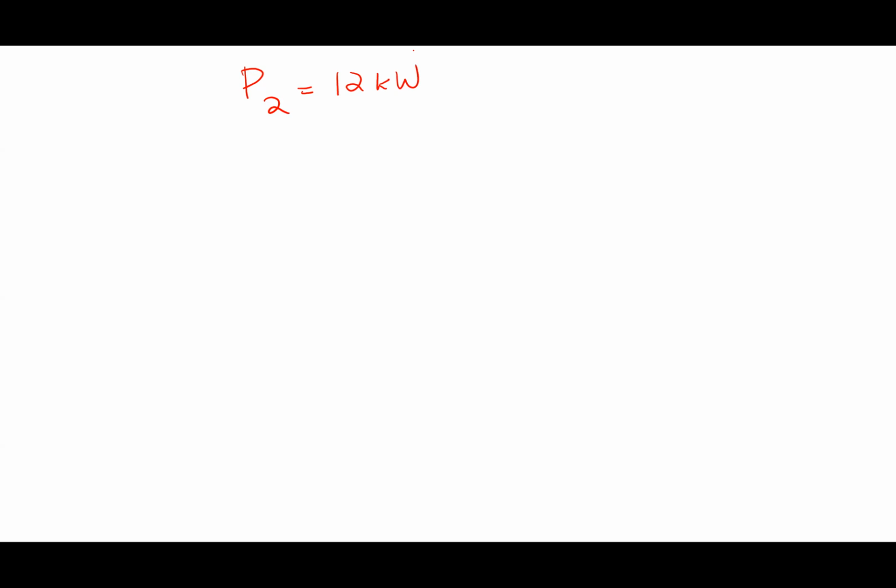They're talking about household type loads, right? That's where these numbers are coming from. And I'm told the power factor was 0.85, which for a house would be a really bad power factor. Is a bigger power factor better for a house? It's a good question. It should be above 0.9. I think in Duke's standard calculations, I've seen they assume about 0.93 for a house. Usually they don't know exactly what it is, but it's usually over 0.9.